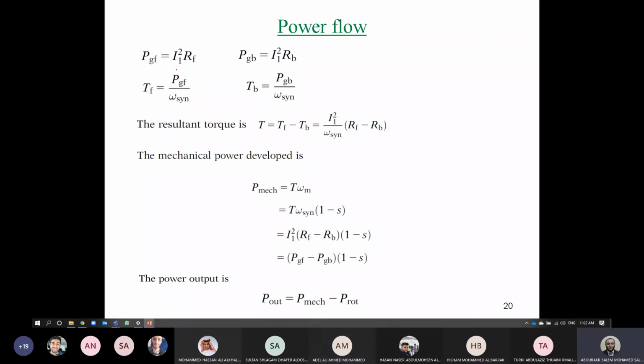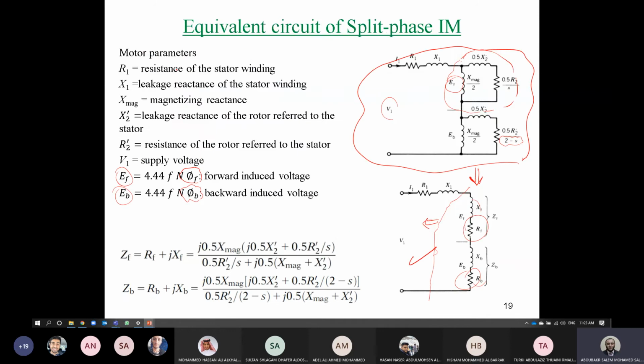Why not line? It's a single phase. There is nothing here called line or phase. The connection is only one phase. There is no star or Y connection or delta connection. So this is one current. So for this type of problems, when you have V given, you shouldn't divide over square root of 3 because it's single phase. Is it right?